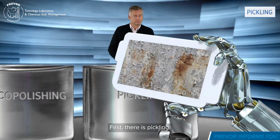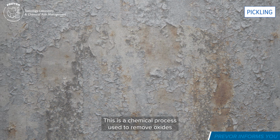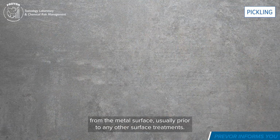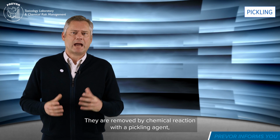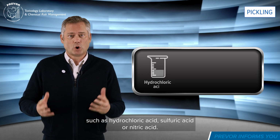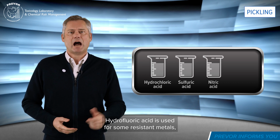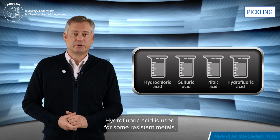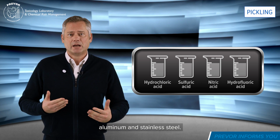First, there is pickling. This is a chemical process used to remove oxides from the metal surface, usually prior to any other surface treatments. They are removed by chemical reaction with a pickling agent, such as hydrochloric acid, sulfuric acid or nitric acid. Hydrofluoric acid is used for some resistant metals, especially in the pickling of alloys, aluminium and stainless steel.